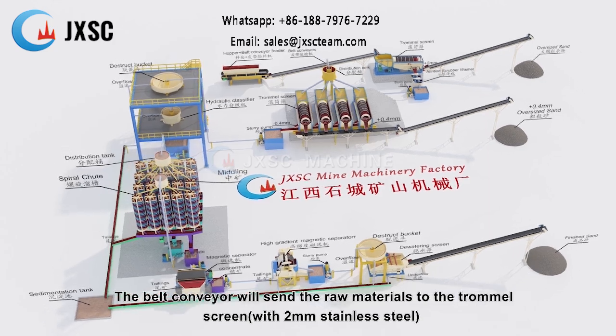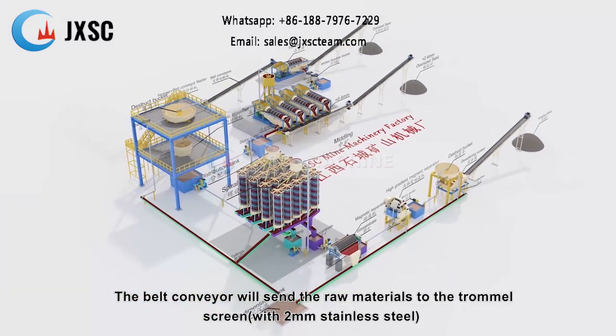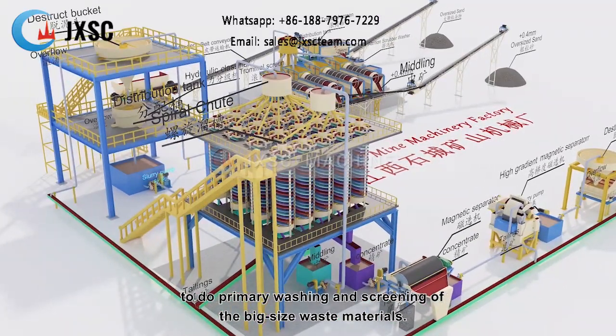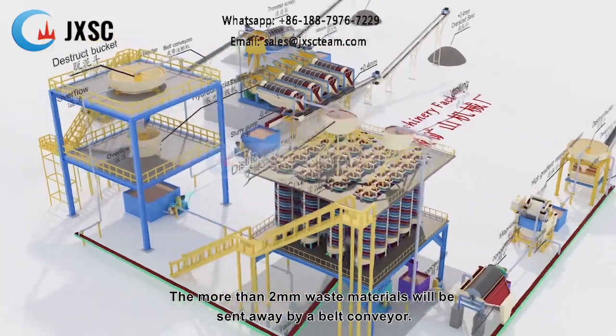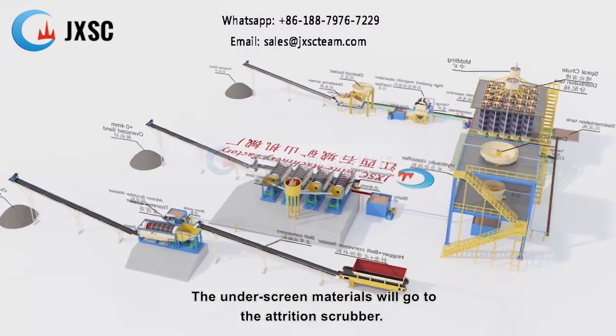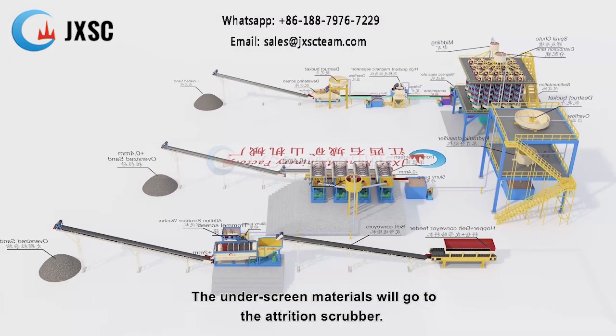The belt conveyor will send the raw materials to the trommel screen with 2 millimeter stainless steel to do primary washing and screening of the big size waste materials. The more than 2 millimeter waste materials will be sent away by a belt conveyor. The underscreen materials will go to the attrition scrubber.